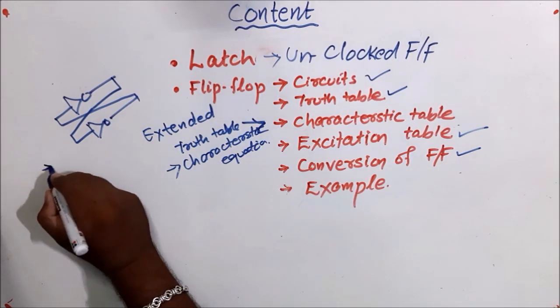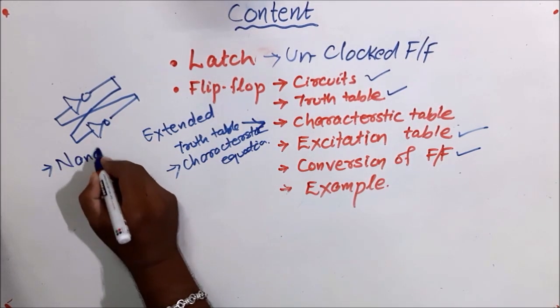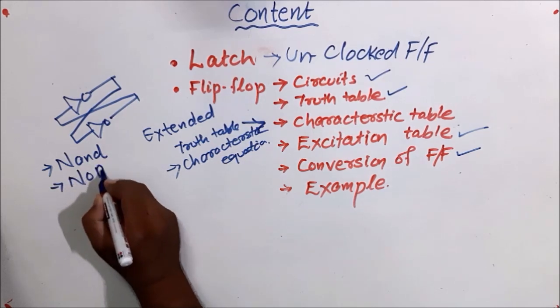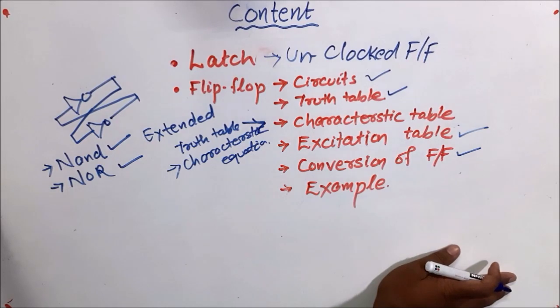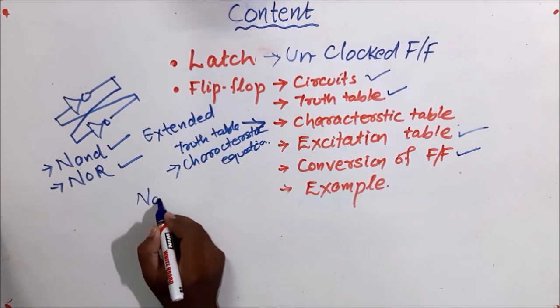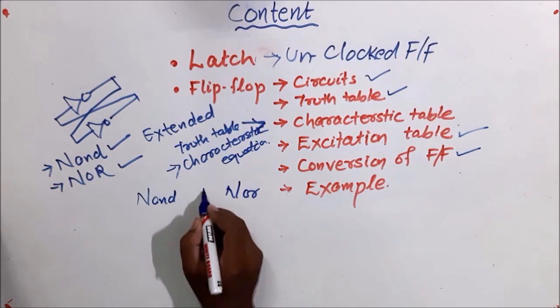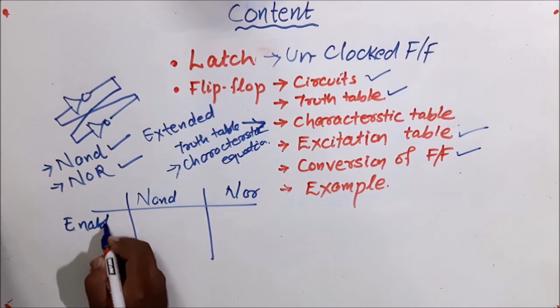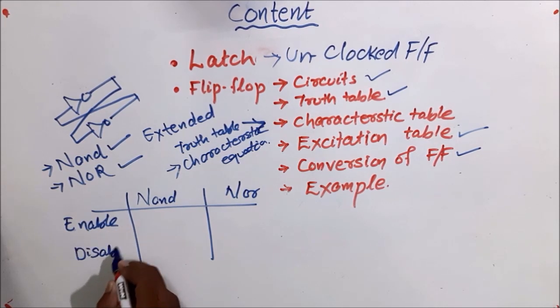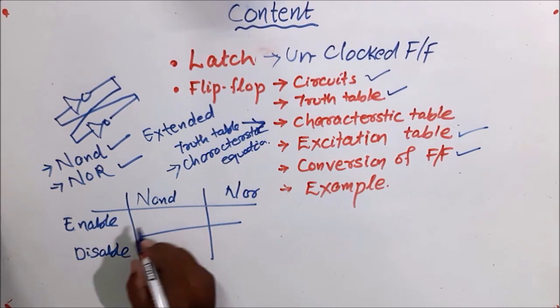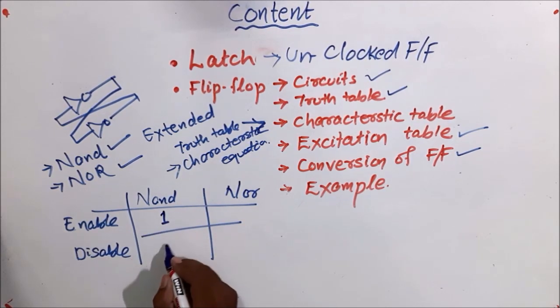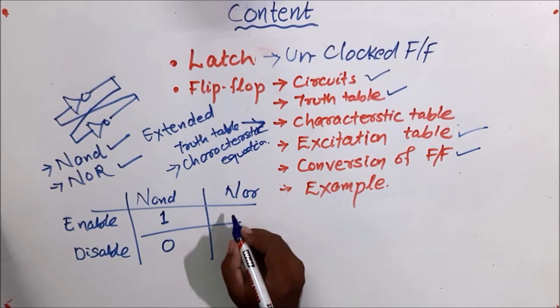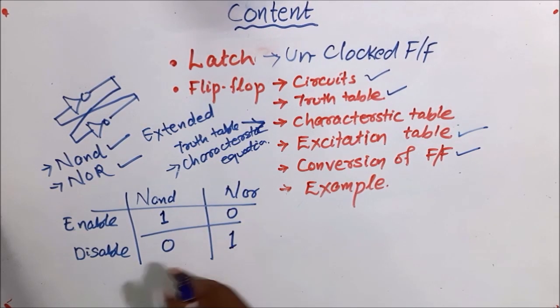That is why we use the NAND gate and the NOR gate. These two gates are universal gates, which is why we use NAND and NOR gates to design latches or flip-flops. Remember, the design is quite similar for the NAND gate and the NOR gate. And remember enable and disable: for the NAND gate, enable is 1 and disable is 0, and just the opposite in the NOR gate, enable is 0 and disable is 1. This is the basic difference.